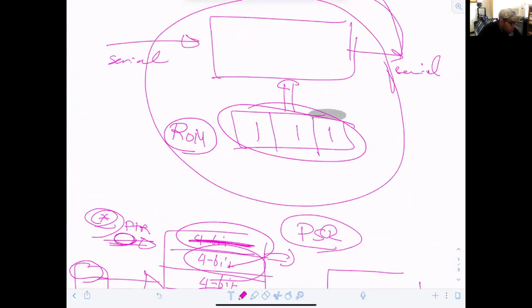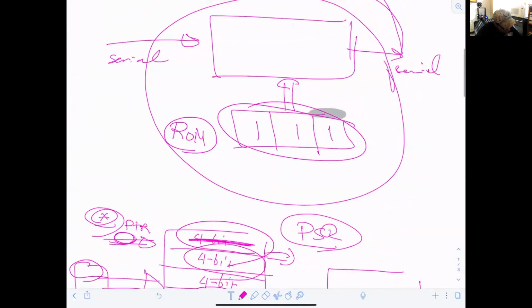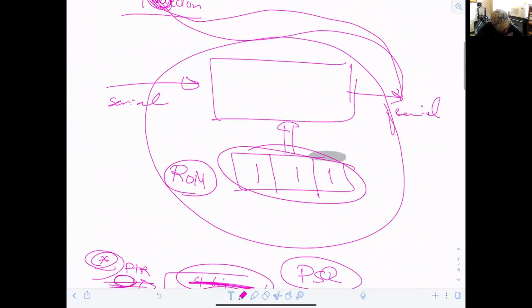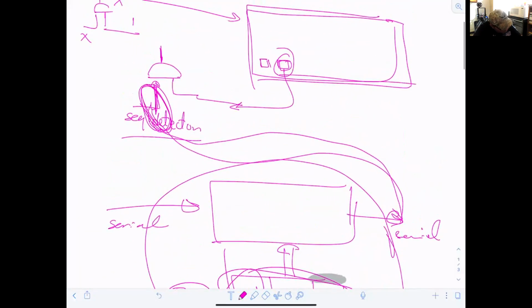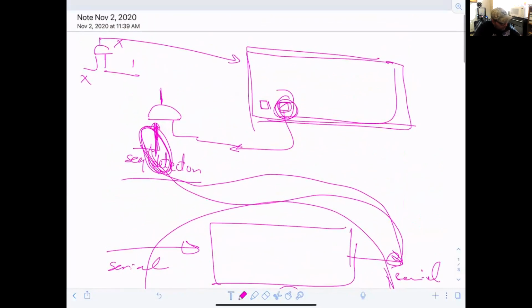It's already set up so that I'm looking for the pattern 111, right? And then every single cycle, this will be compared with part of the sequence. Once you find a match, for instance, three consecutive ones happening, you will issue a one for the output. That one will be going here, ANDed with something already enabled high, then that means the output is 1. That means the counter will be incremented by 1, and so on. That makes sense?